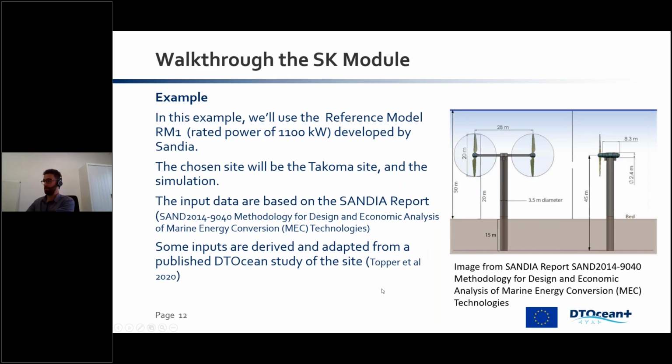Yes, so we stopped at the mooring system, showing it, and just below the 3D graphical representation of the mooring system, you also have access to the forces that are applied on the device due to the mooring system, and you also have the stiffness matrix due to the mooring system on the device. And you can check that if you move the position of the device, the forces from the mooring system will change, and the stiffness matrix will change as well.